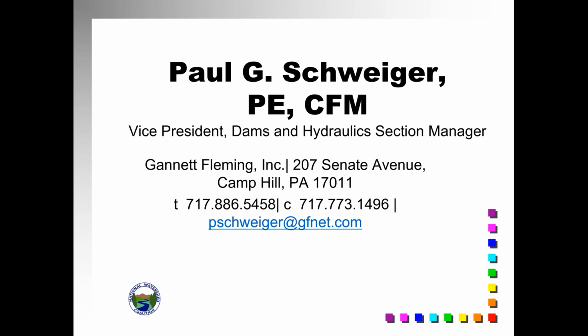The other thing, any modification like that really should be done properly. I think these structures are permitted, and every state has a dam safety office, and it would be a violation to make that kind of a modification without getting them involved. They're really there to help dam owners as well as to look after the interests of the public that live downstream of the dam. And they're an excellent resource. So I would caution anybody from making any modification to a dam without getting approval.